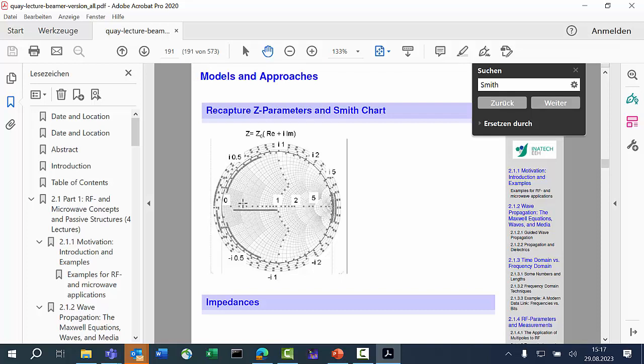Then the impedances we look at will typically be very low. Now you will get the task to put out 200 watts, for example, for a microwave base station, because you want to supply Freiburg. And then you are not interested in talking about impedances in the 100 ohms range. You are interested in impedances in the half an ohm range, and you want to design there. You want to do these steps there.